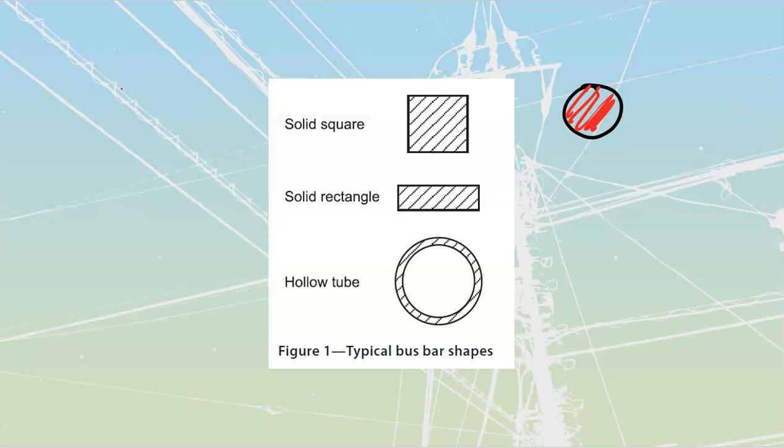What happens, though, when this is going on is that it tends to get harder, just through the compression. Overall, it becomes what we refer to as work hardened. You'll see this on old installations where you'll sometimes have pieces of copper wire that are just incredibly stiff. All it is is that they were hard drawn, is what we refer to.